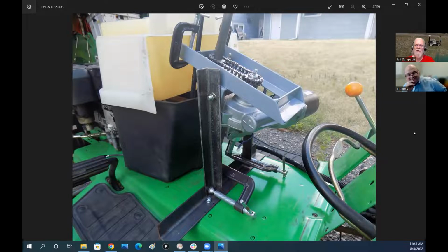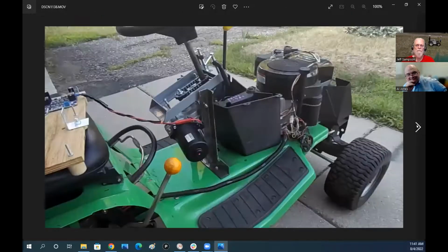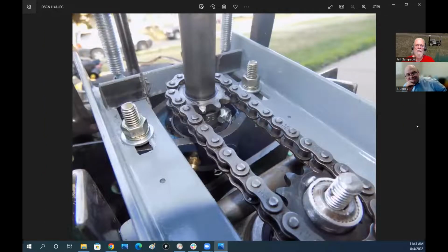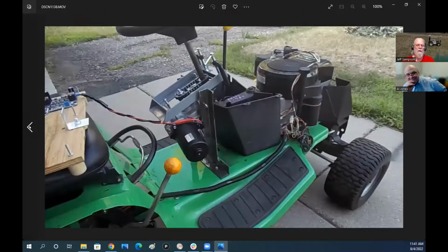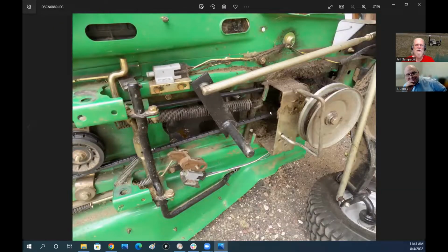And then on the bottom, I could do... where'd it go? Okay, so on the bottom, since this arm moves back and forth, I could just drill a hole in here and get one of those little sensors with an arm on it. So I could measure that moving back and forth, or I could go out on the front, right on one of the control arms on the front and add some other redundant sensor to verify that when I tell it to turn the steering wheel, the actual wheels actually turn.